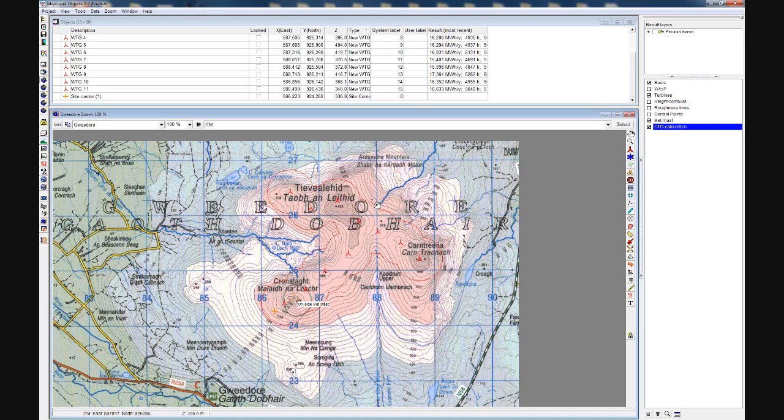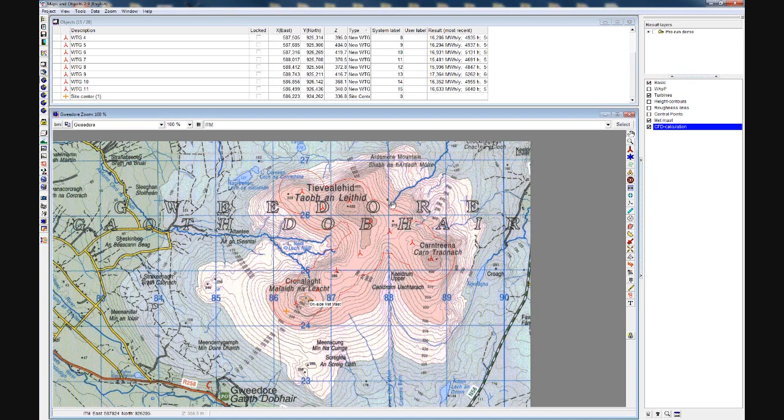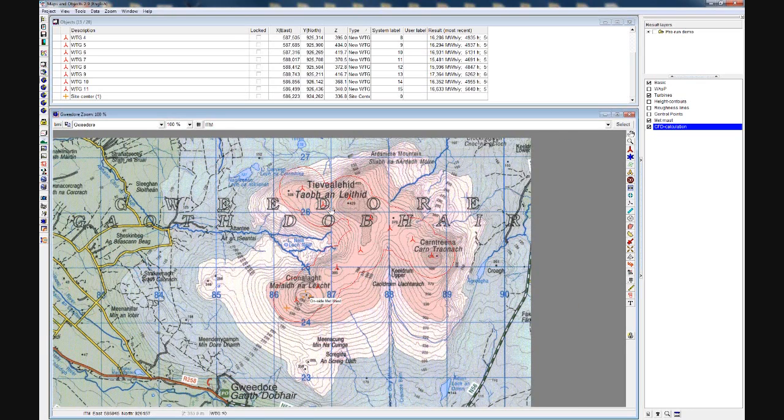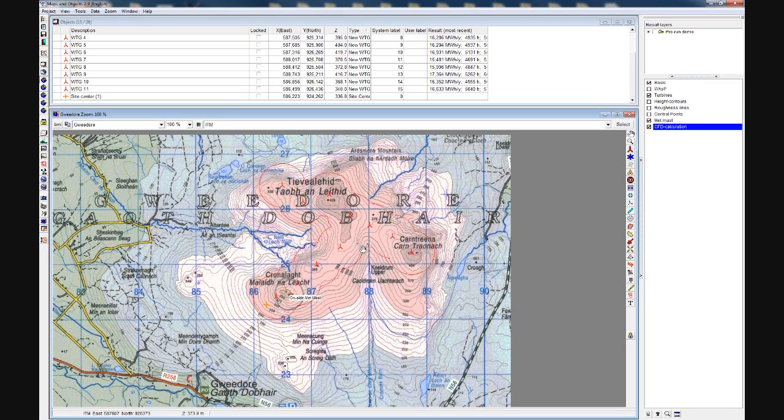Just a second, I need to switch into WindPRO here. So this is the project that I'm going to present today. We have 11 turbines here and a mid-mast located in the southwestern part of the site. It's a site in Northern Ireland. It's a mountainous terrain, so it's perfectly suited for doing a CFD analysis.